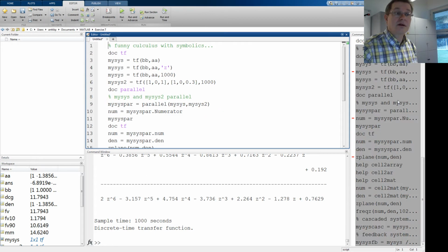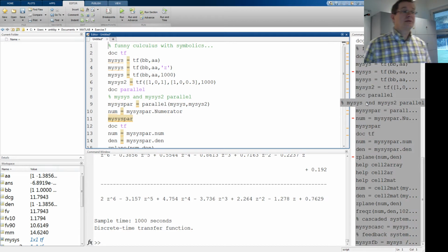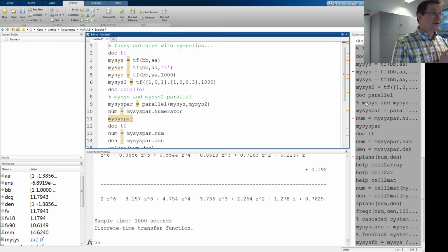Then create a script, and there start fiddling with these KD, KI, and KP values, one at a time. See how they actually affect the step response. When you add some gain on the proportional part, what is the effect?